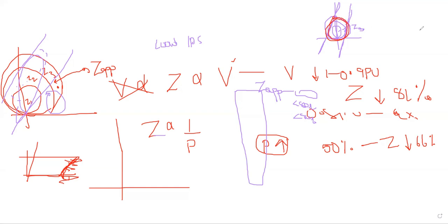Before, the relay was operating up to this portion, all of this portion. Now by adding this load encroachment, I am saying that you should operate only in this. This is the zone now for the relay. Got my point? Maybe there are some changes. See, there is one setting of 5 milliseconds. Suppose within the 5 milliseconds, if this sudden change is happening, the relay will consider that maybe this is not a real fault. It's due to the voltage changes because of the power swing. If it is coming slowly, gradually, then maybe the relay will detect it as a real fault.